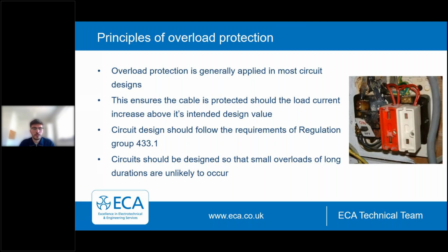Now, in order to do this, circuit designs should follow the requirements of Regulation Group 433.1, and that initially tells us that circuits should be designed so that small overloads of long duration are unlikely to occur. And we will refer to that final bullet point a little bit more.